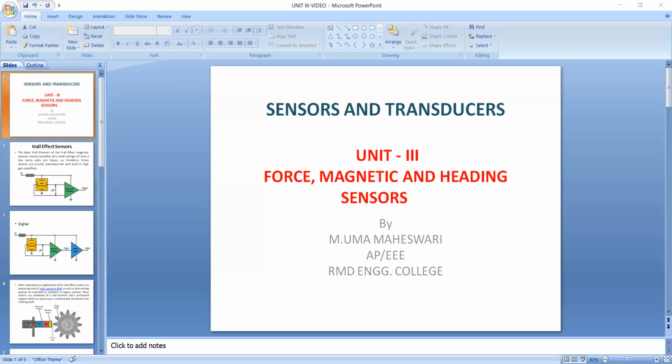So this is the basic principle of the Hall effect sensor. To generate a potential difference across a device, the magnetic lines must be perpendicular, at 90 degrees, to the flow of current and be of the correct polarity, which is a southward polarity.